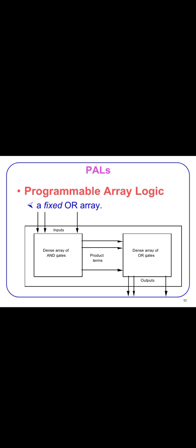By using this, we can implement two easy functions, whereas the AND gates associated with each OR gate denote the highest number of product conditions that can be produced in the form of SOP, that is sum of products functions. The AND gates are connected continually to the OR gates, which indicates that the produced product terms are not shared with the other output functions.